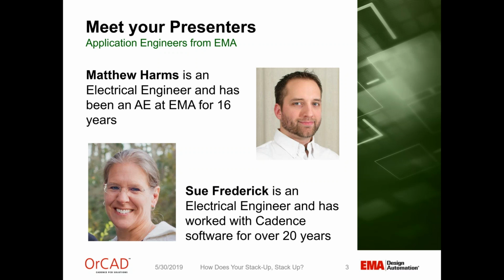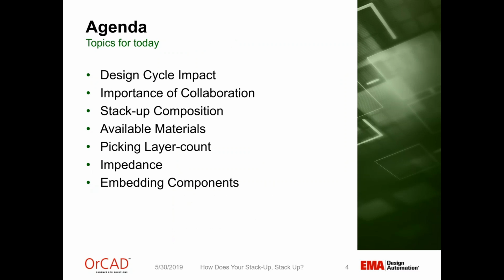All right, thank you, Sarah. So the agenda for today, this is what we're going to be covering in slides, and then we'll be passing it off, as Sarah said, to Sue for a demonstration of some of these features as well. So the agenda is design cycle impact. Then we're going to talk about the importance of collaboration, which is a really big deal, making sure you communicate well with your manufacturing house. We'll talk about the composition of a stack up, materials you can use, how to pick your layer count, how to figure out what your impedance is going to be, and also embedding components.